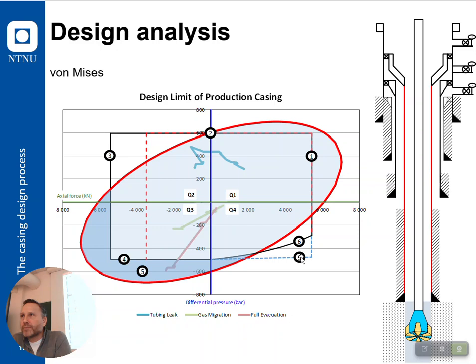It buckles, right? So that's why, and this you'll never see in any standard, or at least Norsok D10 has a figure like this. They don't show conductor pipe with a straight line here or stapled or anything like that. It shows you this curve and the yield. And again, I would not see that von Mises should be on the inside of it. That would not be correct.